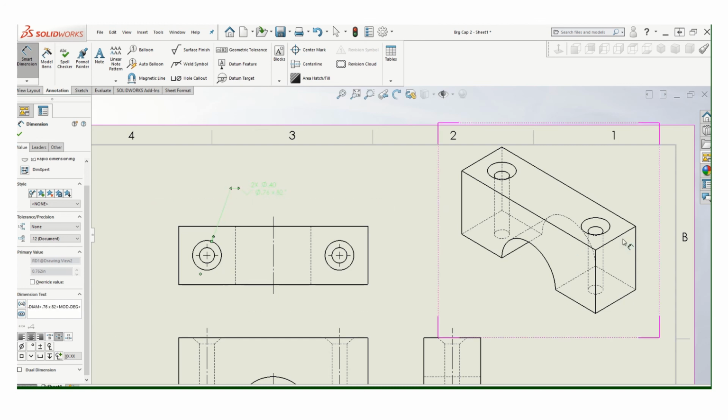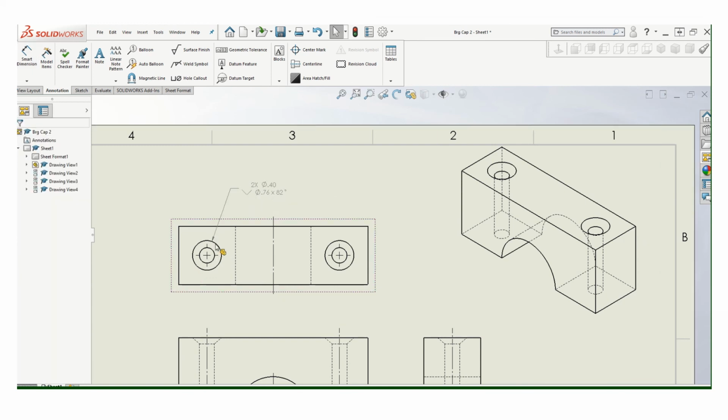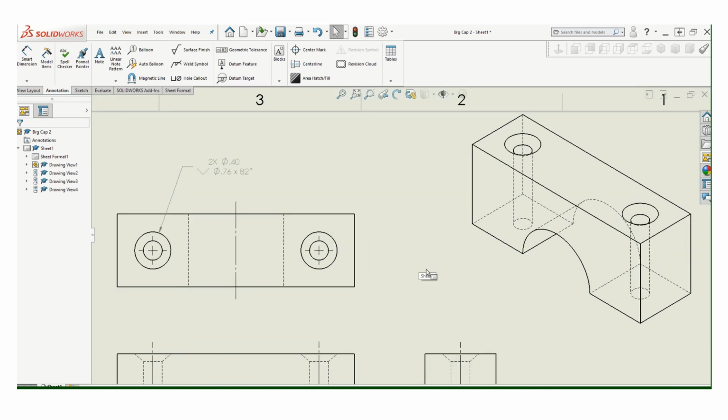And that's the call out you'll see on that handout. That's the way the call out was too, right? So that's a countersink. One dimension, don't put two dimensions on there, and you always dimension it like this with the smaller diameter on top, and the assumption is that it goes through. If it has a through on there, it's okay, but remember, we're trying to minimize the words on a drawing. It makes it a much more international drawing without words. So if it says through, I would typically delete that. Countersink symbol, the big diameter, and that angle, which is the standard angle for a countersink. If you buy a fastener, it's going to have a matching angle on that.